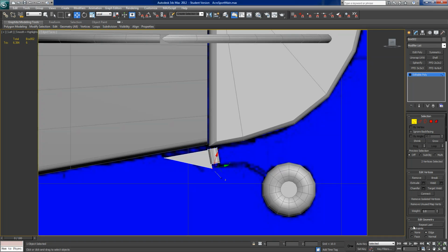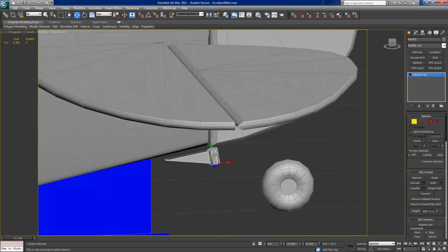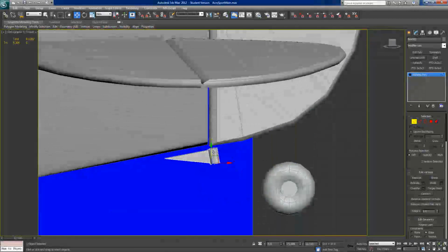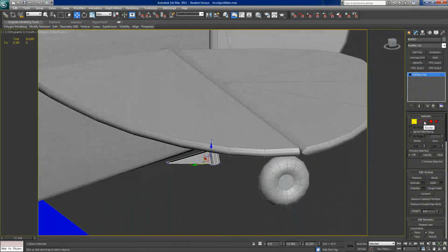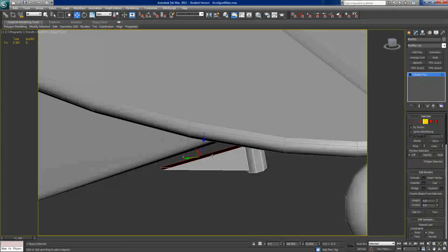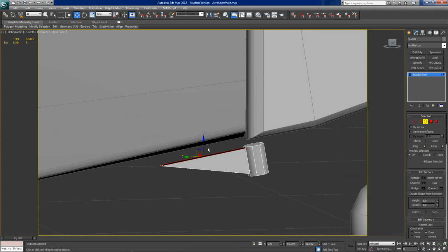And I'm going to put this to edge and go back to view, because that'll just force it to follow them anyways. Okay. Alright, great. So now I'm going to pick this border and just going to extrude up. Cannot do that with edge constraints on, so I'm going to hold shift and pull this up.